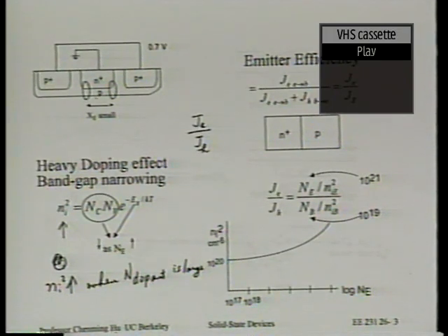Okay. So silicon germanium actually has two benefits. One is it solves this heavy doping problem. Two is it gives us a drift field. It actually does two things. All right? Can you think of a way to use silicon germanium to only solve the heavy doping effect without introducing a drift field? Can you see a way to do that?